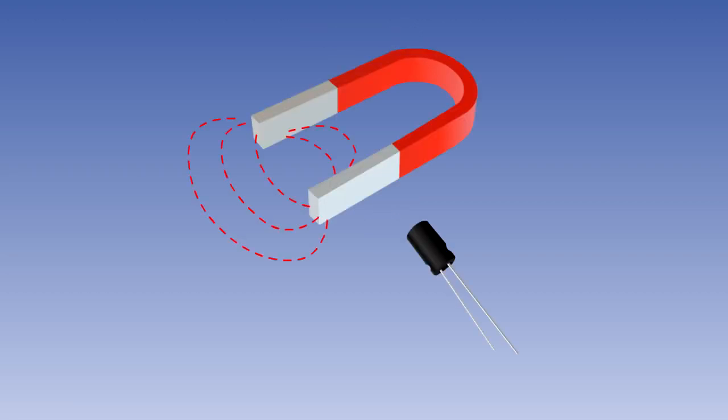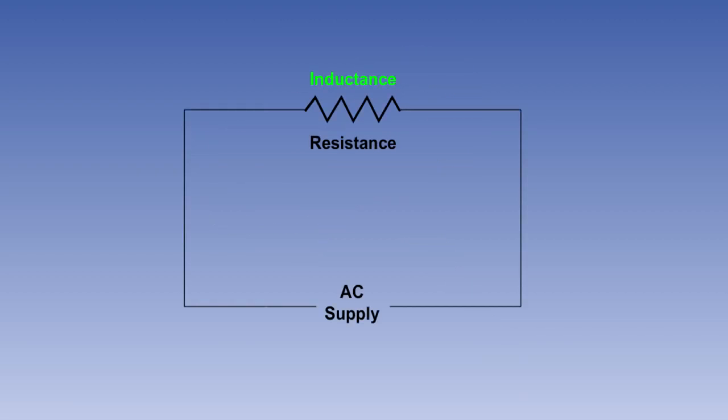There are very few AC circuits in which the current is affected solely by the applied voltage and resistance. In most AC circuits, because of the ever-changing values of voltage and current, the current flow is influenced by the magnetic and electrostatic effects of inductance and capacitance. There is no such thing as a pure resistance when considering an AC circuit. All resistors, even a simple piece of wire, have a property known as inductance as well as resistance.